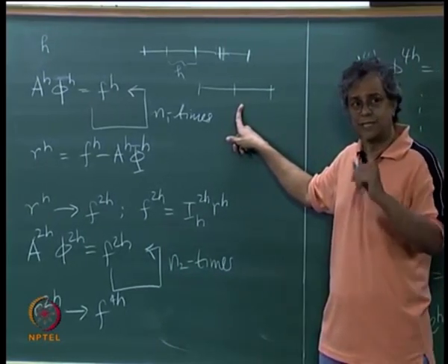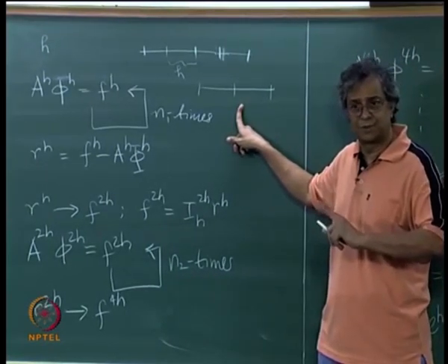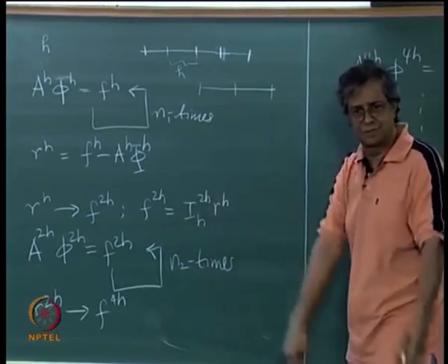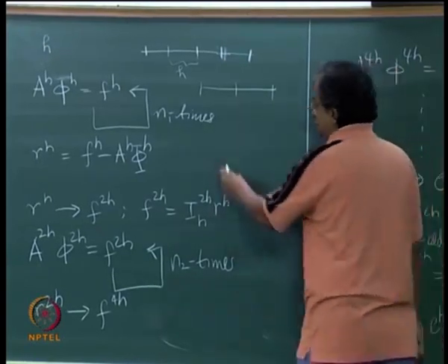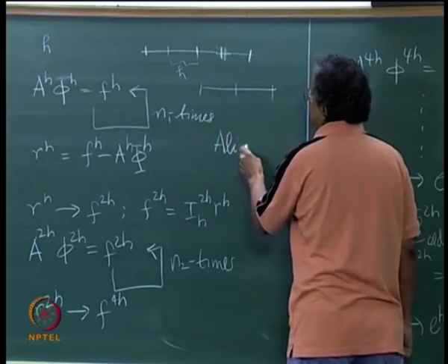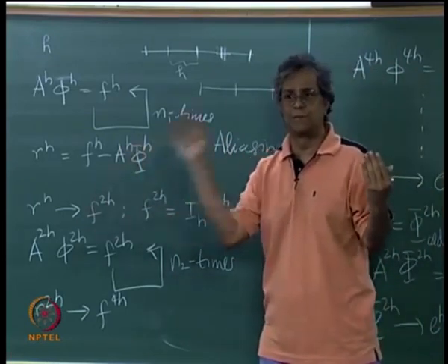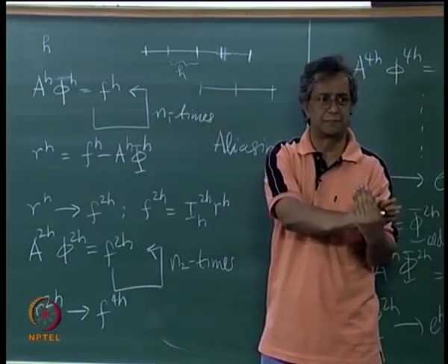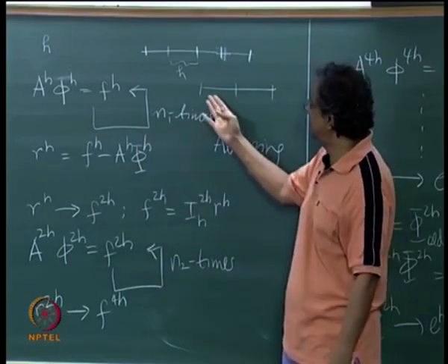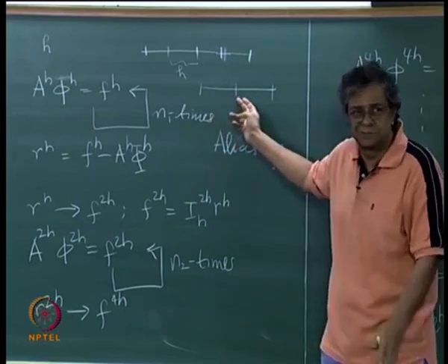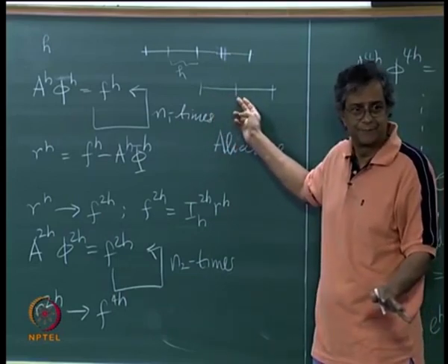Otherwise, what will happen is what the signal processing friends in electrical engineering call aliasing. That high frequency error will fold back into the low frequency end, and we will start getting a residue here which is spurious, which is not the right residue.